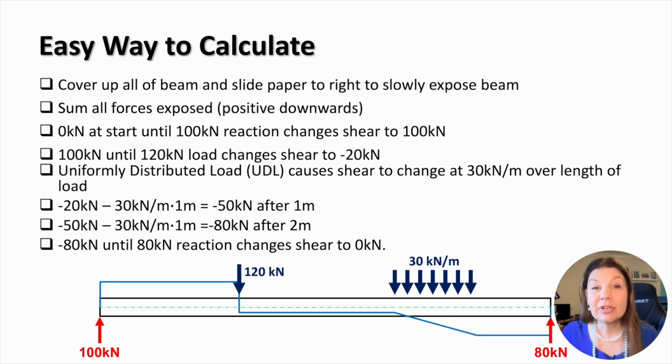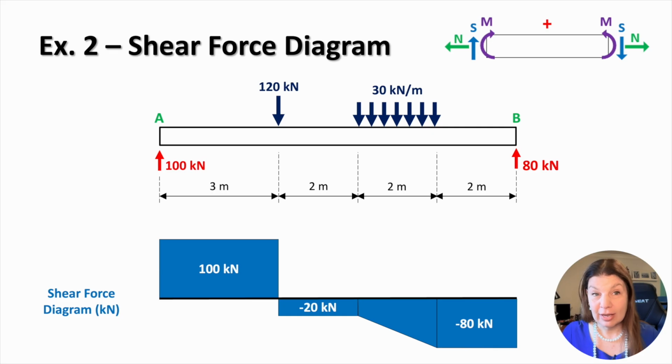This is the key difference introduced by a distributed load. The shear changes at a constant rate rather than by a sudden jump. We can now draw the shear force diagram.